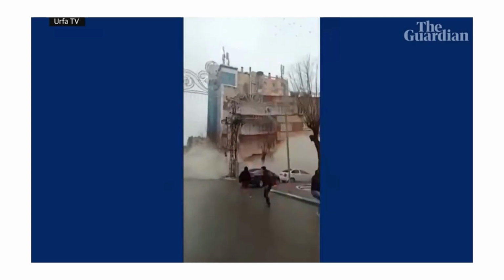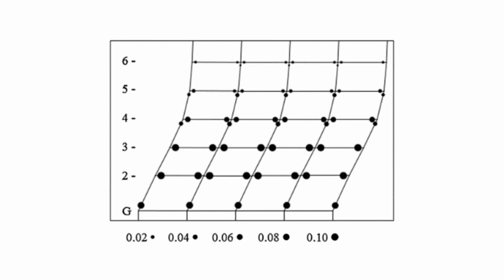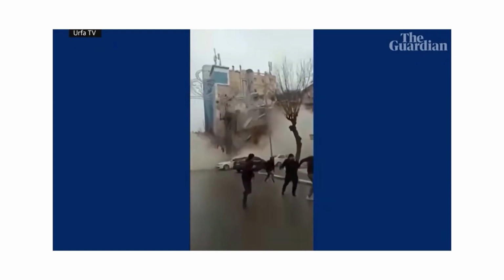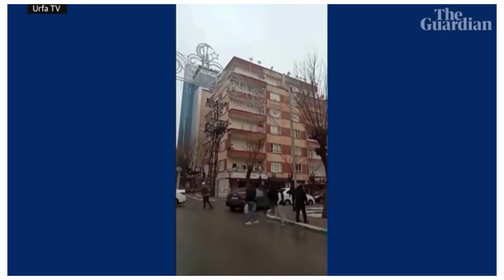So what happened on the ground was, after the first shock, a large number of buildings developed cracks, inelastic deformation in the beam and column joints, and got partially drifted from their position. And these structures are very susceptible to a high P delta effect, that is, the second order moment, if the slightest disturbance is further experienced. But the unexpected aftershock of huge magnitude immediately produced a high P delta effect in the damaged drifted structure, and that led to the overall structural collapse.